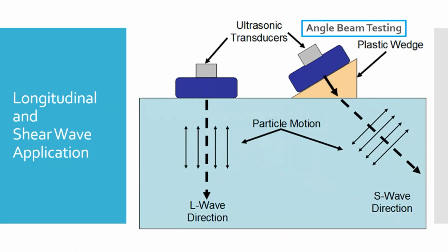But what that allows us to do is that shear wave, now you can see, a couple things you got going on. I'm sure you've all seen a straw in a glass of water, and where the straw goes into the water, at the surface of the water, it looks like it's bent, right? Because of the refraction. Well, sound has that same refraction when it goes through an acoustic interface.